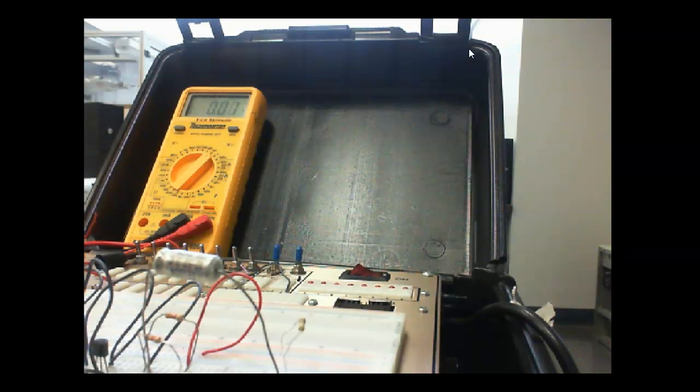So this is telling you, if my bias is the same and my gain drops down, what would be the first place to look? Well, I look at that bypass capacitor. First of all, I'd see if my input was right. I'd check that bypass capacitor, because that changes the gain, right? What if the gain goes up and my bias is correct? Well, that means I'm going to look at the load, right? You understand what we're saying? But the next thing I'm going to do is start working on the bias. So step 10, what am I going to do?